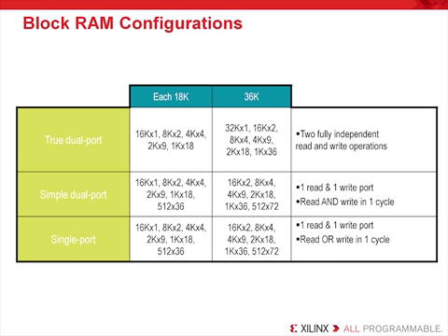This slide is just showing you the supported sizes for the block RAM resources based on your selection of the functionality for your memory, whether that is true dual port, simple dual port, or single port. So if you're trying to plan this out, you have the information right here. But most customers just build the memory with the core generator and evaluate their configuration later. After all, the core generator will build your memory from these predefined sizes no matter what.